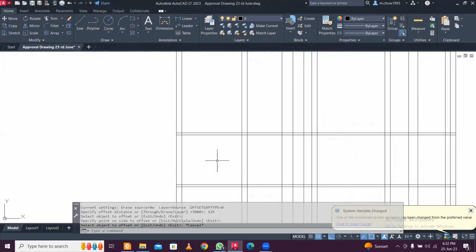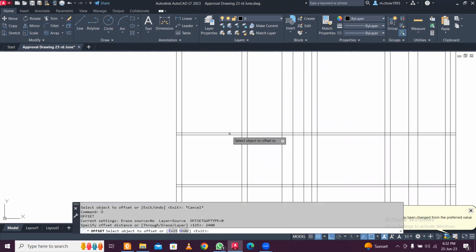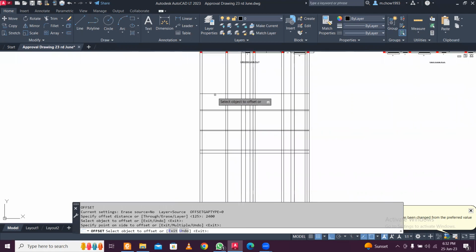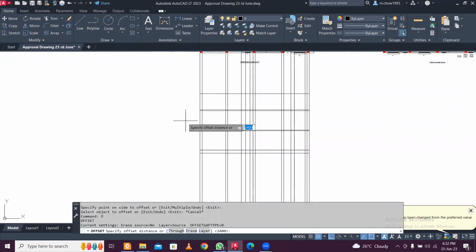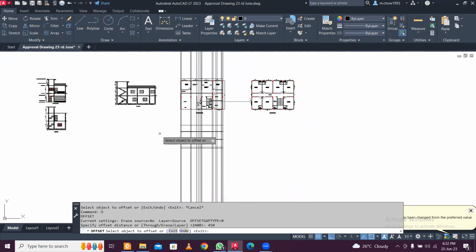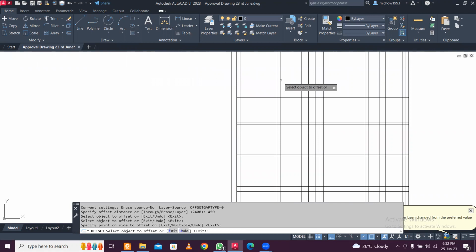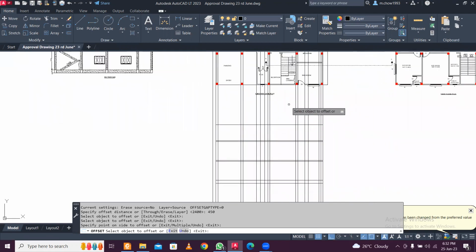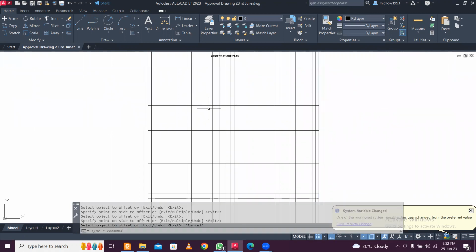feet. So we just take this, and this will be our headroom height, and this is done. We'll extend these things at a distance of 450 mm, the chajja, so that the rain doesn't flow onto this portion. So this extension we'll do here like this in this direction, 450 in this direction. This is where the staircase is. Okay, this I'll take later. So this direction also 450 mm we can take.